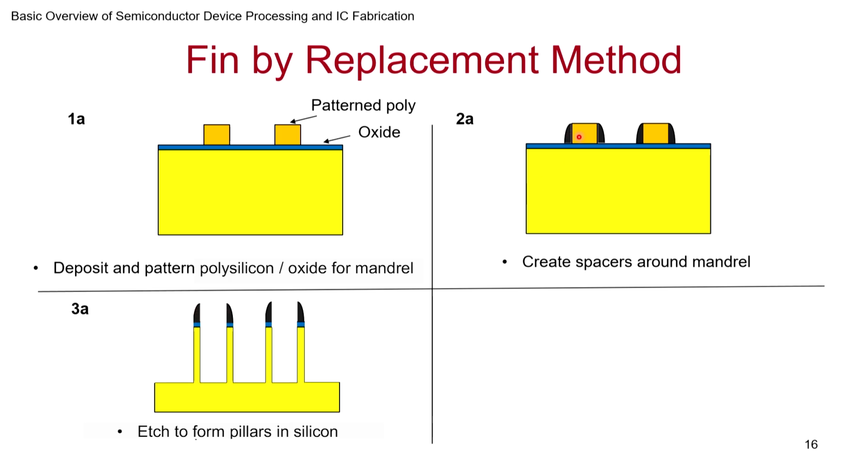Okay, so the hard mask that you built by photolithography earlier is now being built by building a spacer around the gate structure here. It's a really neat and cool idea, where you are able to get 4 structures where earlier you could get 2 structures. So you are able to build 4 pillars next to each other.